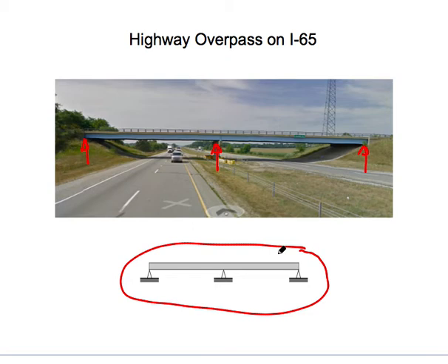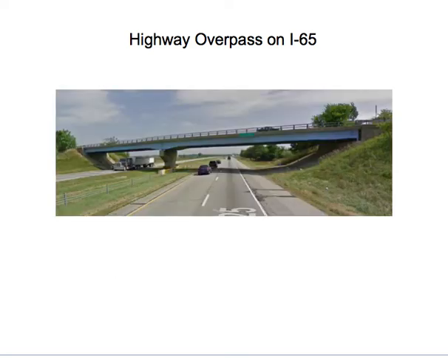You know that's a real problem because that's the first step you go through when you look at a stress analysis in a component: you've got to know the reactions. And from the reactions you get the internal resultants. The resultants give you the stress. But that critical first step we can't do. And that's an issue we're going to deal with all semester long in looking at indeterminate structures.